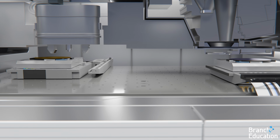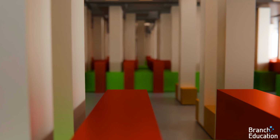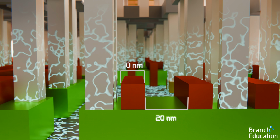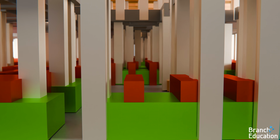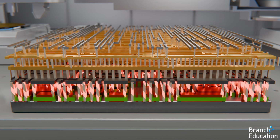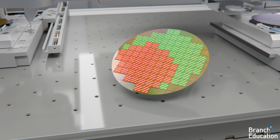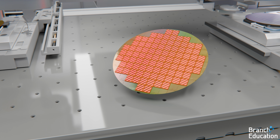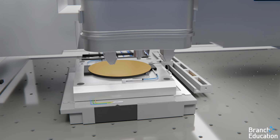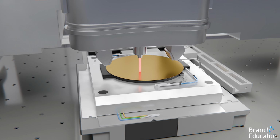The reason for acquiring this level of perfection is that when we look at the nanoscopic layers of the microchip, which has wires and holes that are only 10 to 20 nanometers wide, if one layer is more than a couple nanometers off the previous layer, then the electrical connections won't conduct electricity correctly. And if an entire layer is off, then every single chip will be catastrophically destroyed. To make sure that the layer being patterned is perfectly aligned with the previous layer, the entire wafer is thoroughly measured by the alignment sensor.